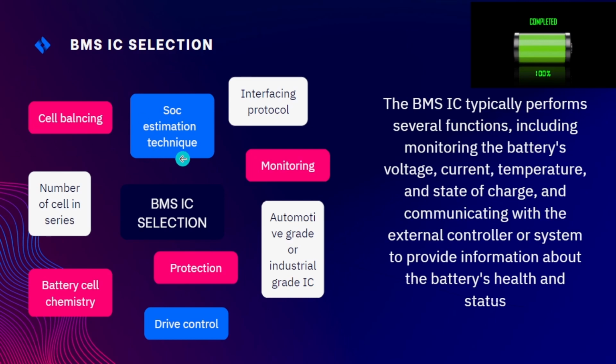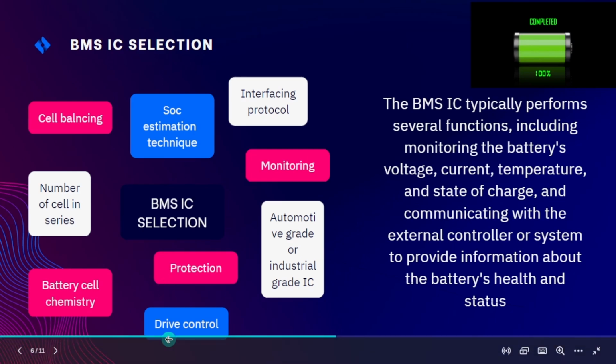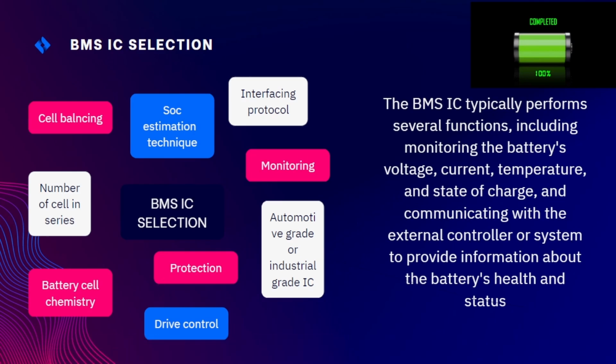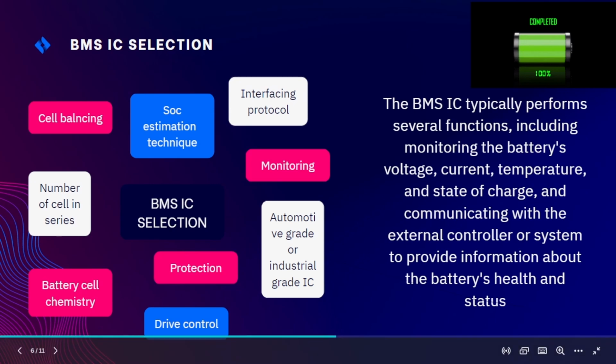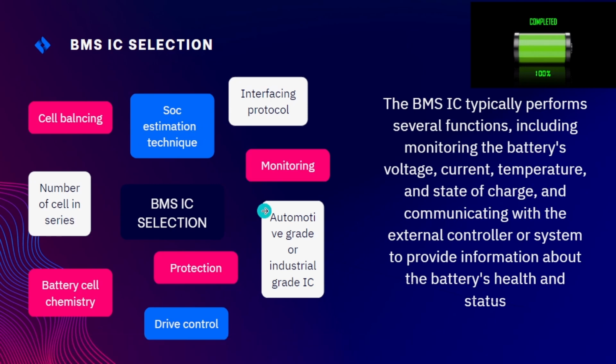So next one is the drive control. Another consideration is a means of control of the battery from either the load or the charger. This can be done mechanically through a contactor external to the IC, or it can be done internally in the IC through a field effect transistor, that means the FET, such as a MOSFET transistor.